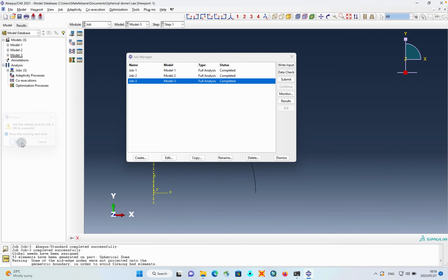So this is now me converging. I'm doing mesh convergence, because I'm decreasing the size of the element to see if my answer converges to what I want. That's basically what I'm doing. Of course, when you make your element sizes small, you are increasing the computational time, or the time it takes to reach the solution.